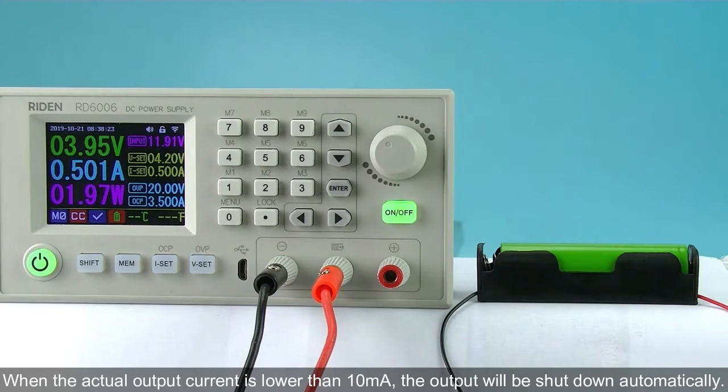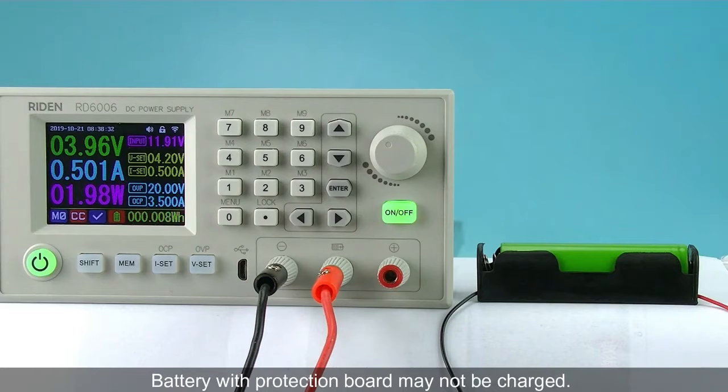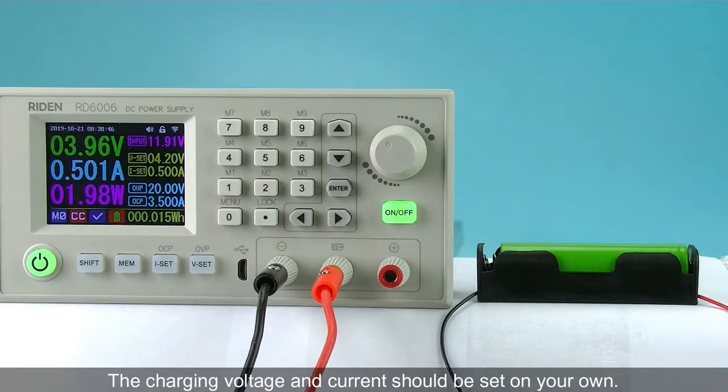When the actual output current is lower than 10 mA, the output will be shut down automatically. A battery with a protection board may not be charged. The charging voltage and current should be set on your own.